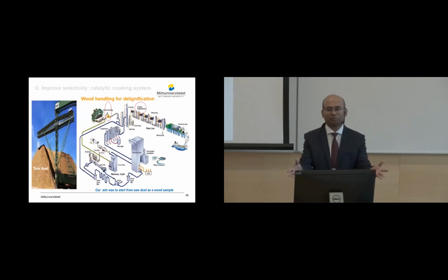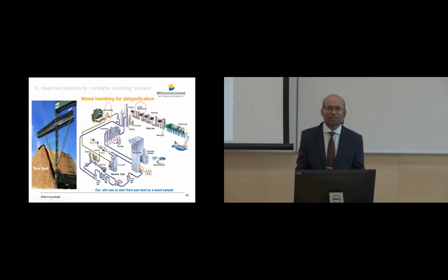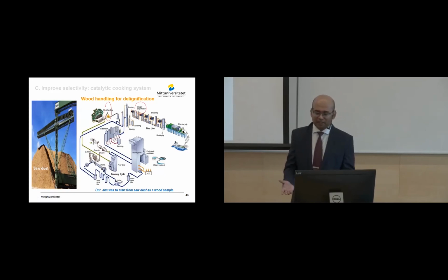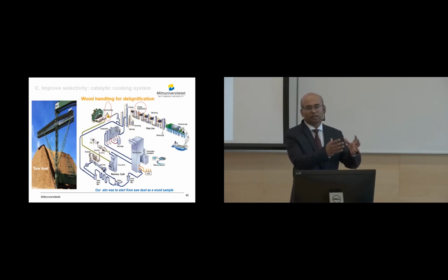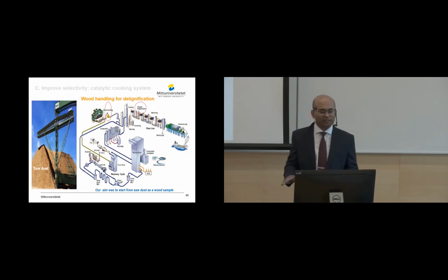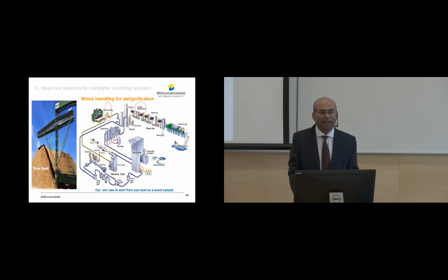So this is very familiar to the pulp industry. Look at this side. We have wood and sawdust used for pellets and also energy purposes. We have oxygen delignification. Why do you choose oxygen delignification? Because the purpose is multiphase, with chemical reactions during pulp production: we have a better cooking process, not extending the cooking, less bleaching chemicals, higher brightness, and lower content. So for better pulp properties, we use oxygen. So we can integrate this process here to increase selectivity and production of the vanillin.